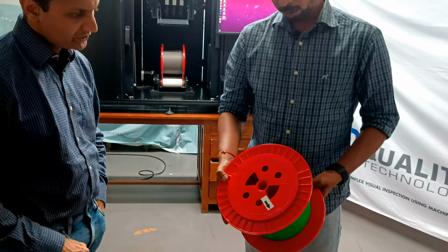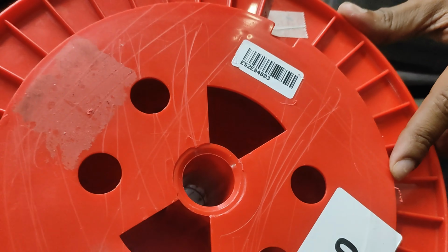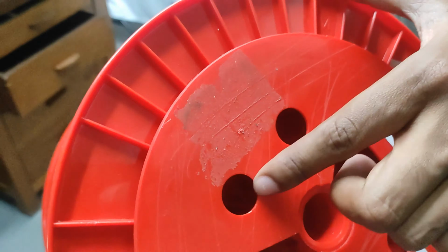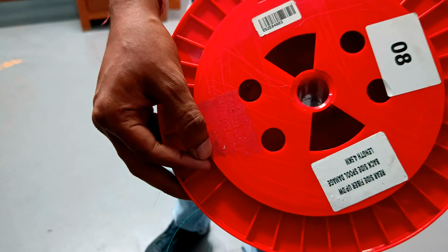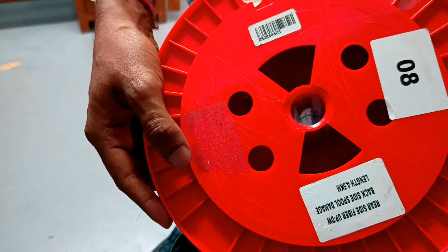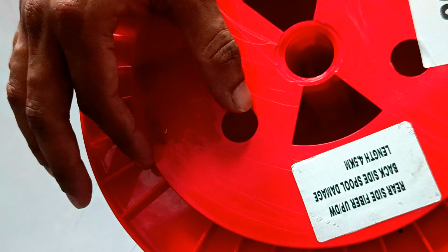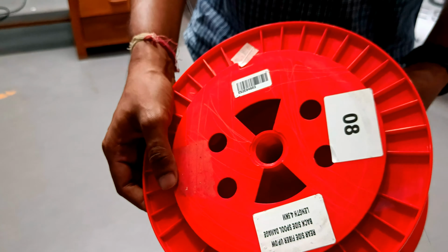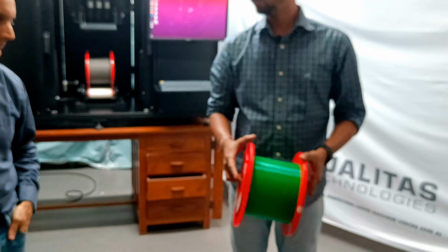Okay, and on the flange? On the flange, there are defects such as scratches. As you can see, there are some observable scratches here. These spools are recycled, and the residue of the previous stickers is also deposited here, which can attract dust. So this is also undesirable, and we have to inspect for this as well. Along with that, if there is any manufacturing defect or any damage caused in transportation, then we have to identify that as well.